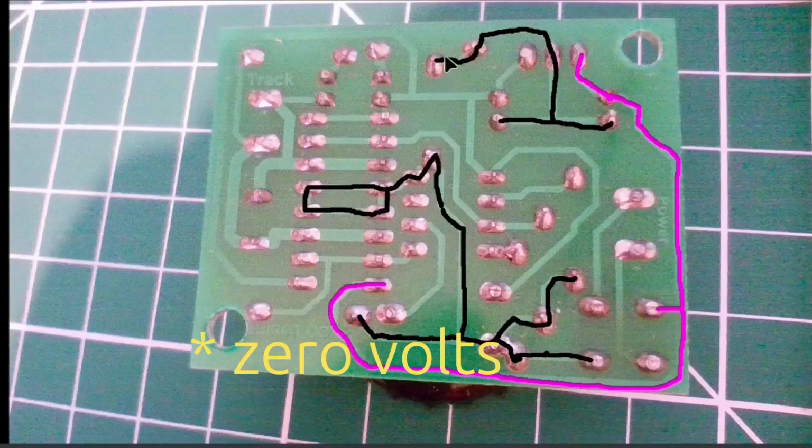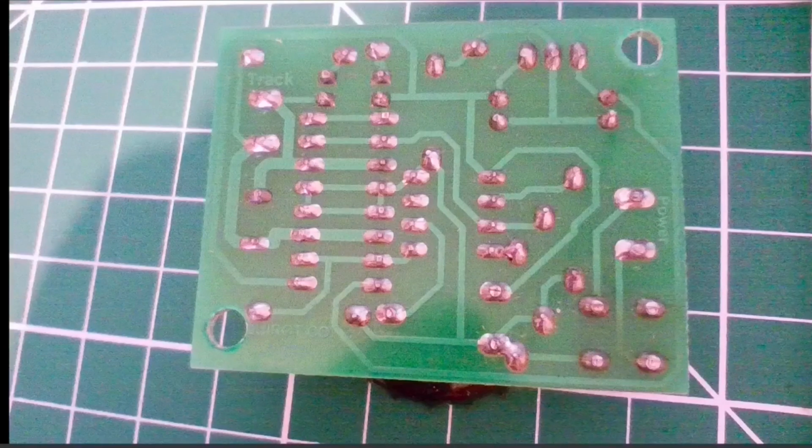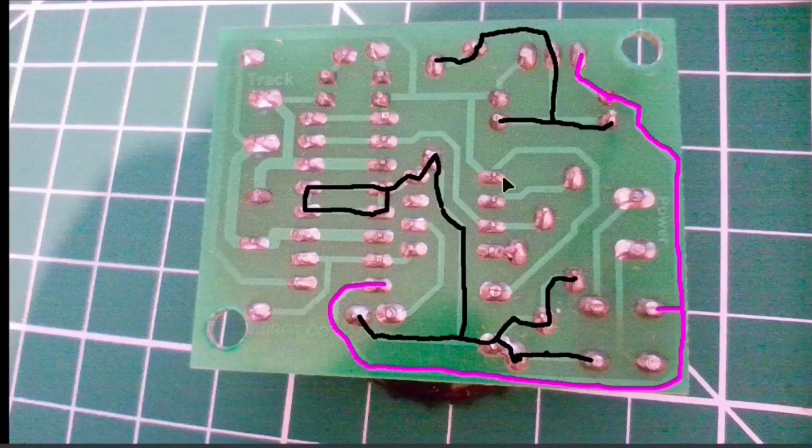There's a gap in the 12 volts here, because if I go back to here, this is a 0 ohm resistor. It's quite commonly used in single-sided circuit boards, because you often get a case where you want to connect this pin here to this pin here, but you've got 2 tracks in the way. Because it's only a single-sided board, the only way to get there is to take a link on the other side of the board.